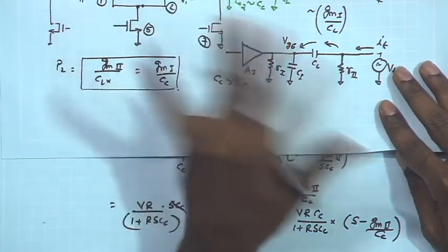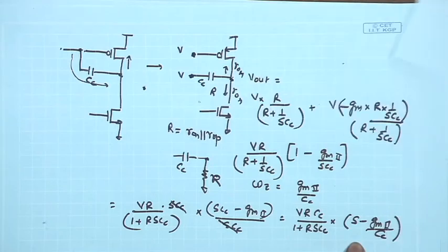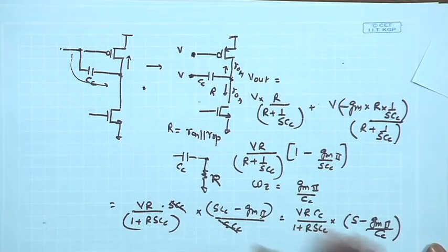And if we assume that it is also higher than the second pole, we are having 40 dB per decade slope before this 0 comes, because the earlier two poles are going to contribute overall 40 dB per decade decay in the gain before this 0 approaches.